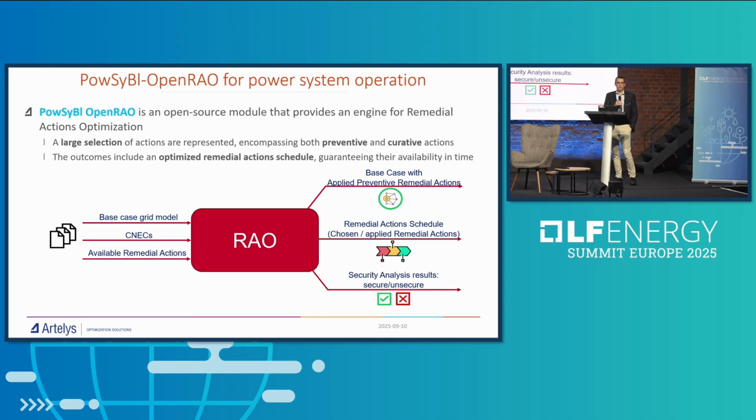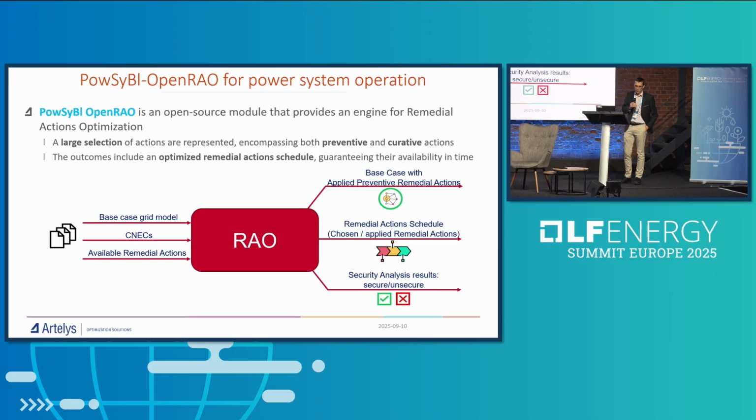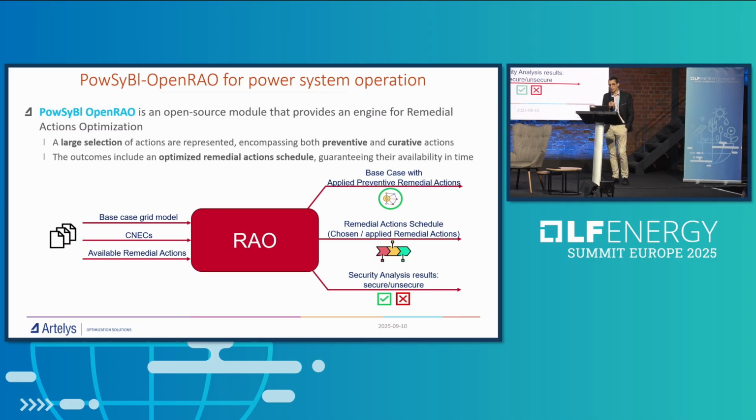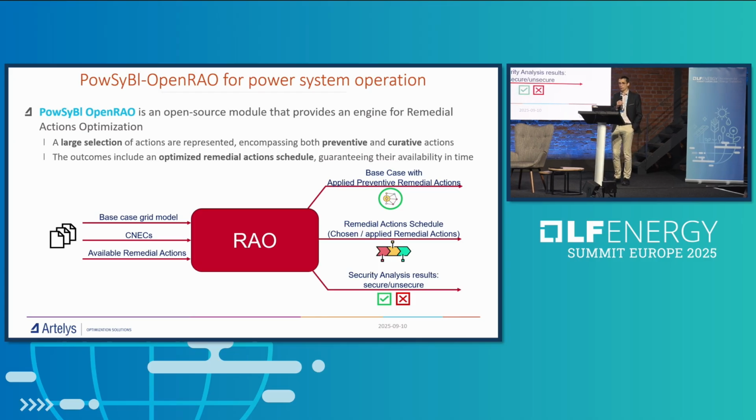You take the grid as it is forecasted for tomorrow, and then it's full of congestion, because the result of the scheduling of the generation results in issues that were not anticipated, because there is more wind, there is less wind, and also because the generation is scheduled at the zonal level, and sometimes the zones are not adapted to the real flow pattern, so that you have to do redispatching within bidding zones, as was shown in the previous presentation.